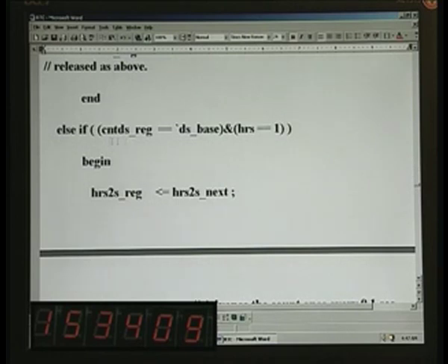And the next condition is the counter decisecond, we want 0.1 second. So when that is equal to the set value we have defined earlier, and also the hours push button is 1, okay, only if this condition is satisfied do we need to increment the counter, right. That means we are incrementing every 0.1 second, okay. So 20 is what we put earlier; just now we have seen 20 times 0.1 will be 2 seconds. So that is how you get that, okay. Is it clear or is there some problem?